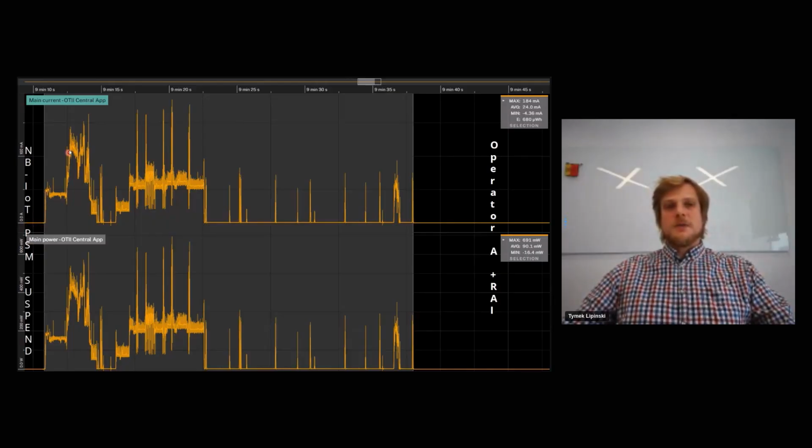We load the system, activate, configure it, search for a network, send some data, receive some data, send the release assistance indicator to the network, and the network says, okay, no data in, no data out, let's kill the RRC. It releases the RRC, the modem goes back into paging, anything for me, preparing for suspend mode, and it goes to sleep below 4 microamps of current.